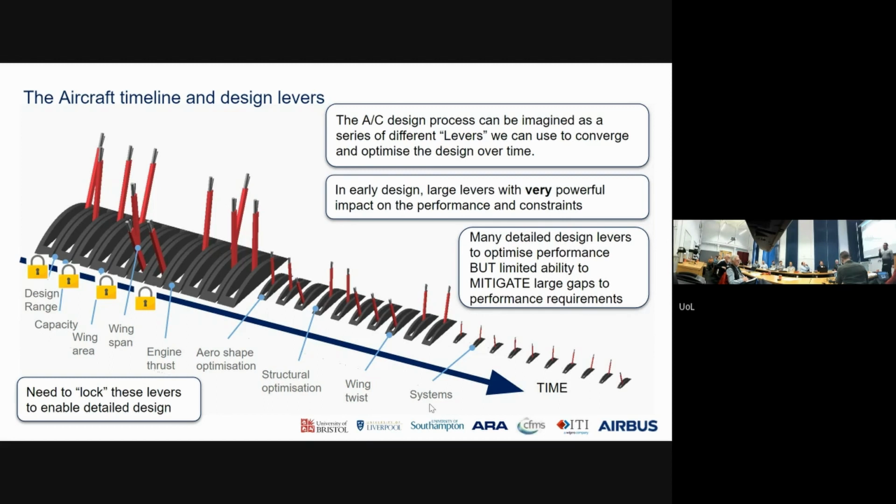And this is an important part that, for me, in the early phases, you're not trying to design an optimized, reliable aircraft. You're trying to ensure that the selection of your design parameters gives you sufficient confidence that you can design an aircraft that will meet your performance guarantees and be certifiable and safe. So you're not doing the full design, you're trying to position yourself so that you have sufficient freedoms available that you can exercise these levers to achieve your goals. And this is an important distinction.